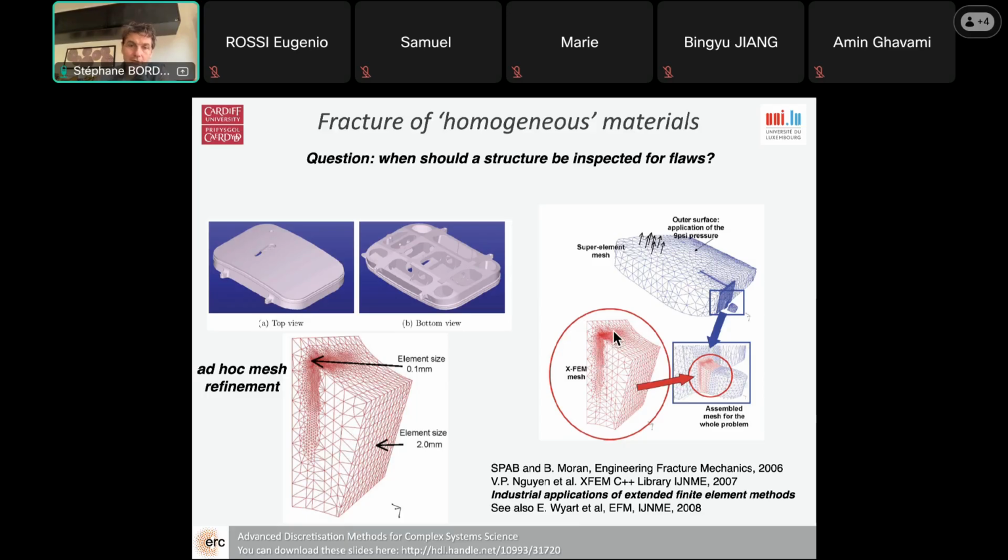So the loading on that is effectively the negative atmospheric pressure, because you pressurize inside the aircraft, which means that you have an internal pressure pushing towards the outside, and the pressure inside the aircraft is trying to push that thing out of the aircraft. This is why if you open that door during a flight, everybody would be sucked out of the aircraft, because the pressure inside is higher than the pressure outside.